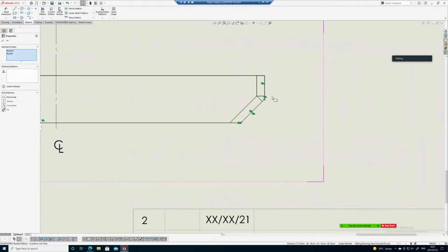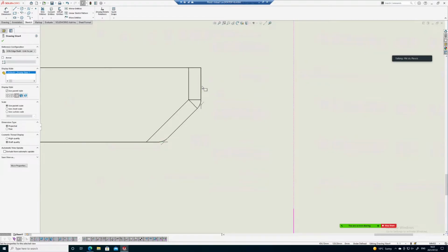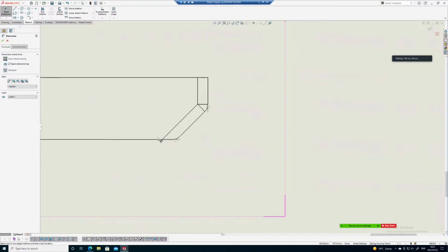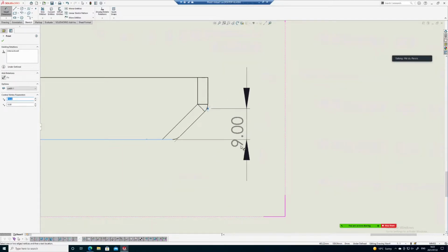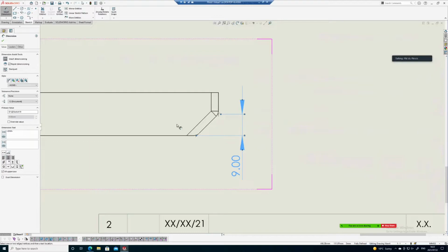That's all you're doing by putting a virtual sharp in: you're saying, how do I represent what this shape looked like before we put the radii in? Because that's the shape that I need to dimension. So for instance, we actually don't need this one, we only need the top one, depending on what you're doing. But if I want to know what the theoretical height is, that virtual sharp allows me to do that.